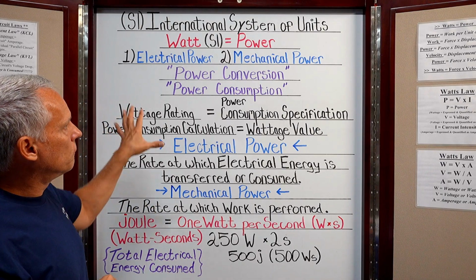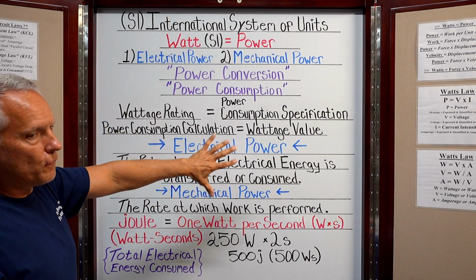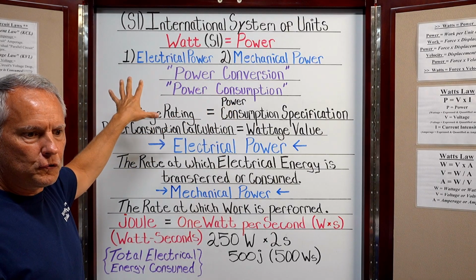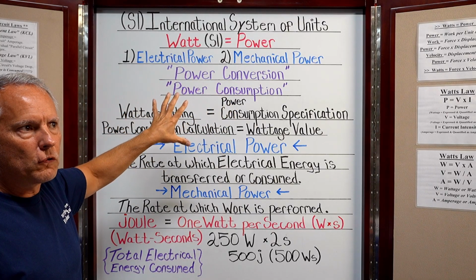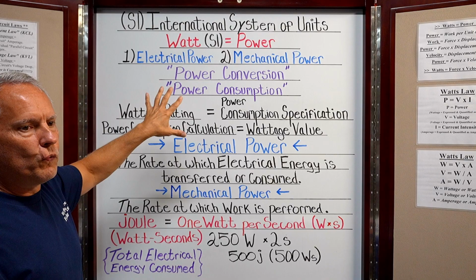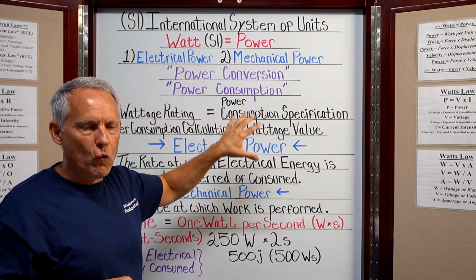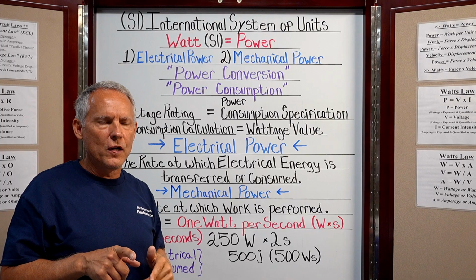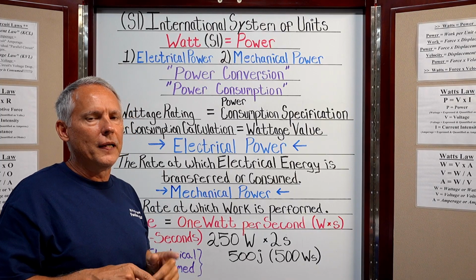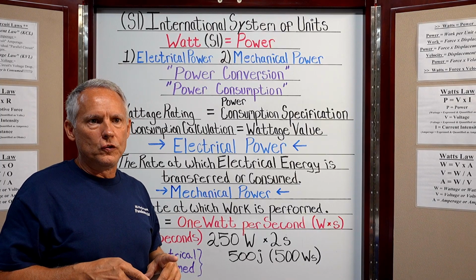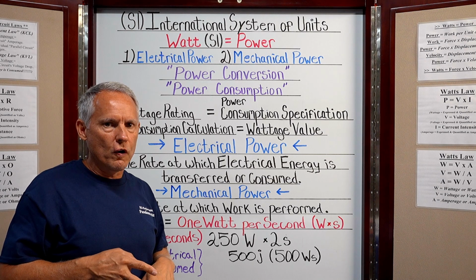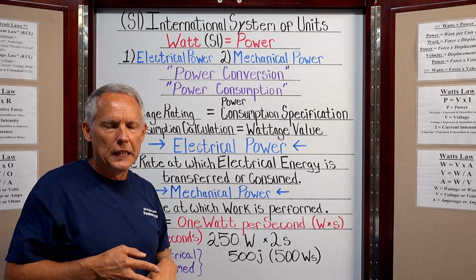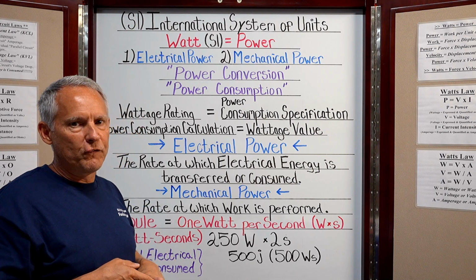But I'm now going to basically get rid of all this, and I'm going to make some calculations. And we're going to talk about how when you calculate amperage and voltage from wattage, the answer that you come up with, although accurate, might get you in trouble, okay? Because there are a few things you've got to know about inrush current, also known as surge current, that we're going to have to discuss, okay?